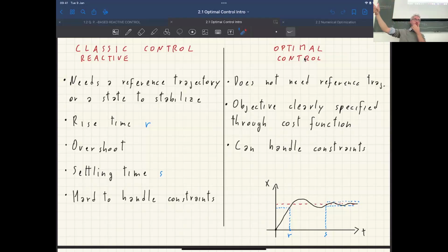So those are the examples that we did also when reasoning about joint position constraints. If you want to avoid hitting your joint position limit, you need to start braking maybe half a second before. You cannot wait until you're this far from the limit to start braking, because at that point it's too late, and whatever you do, well, you're cooked. So that's the reason why reactive control methods typically struggle with this kind of position-related constraints.